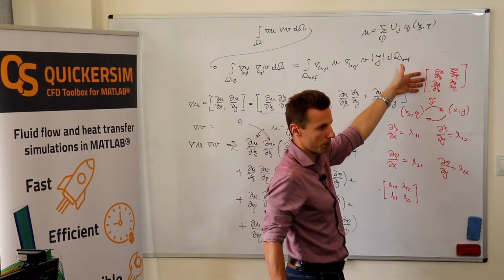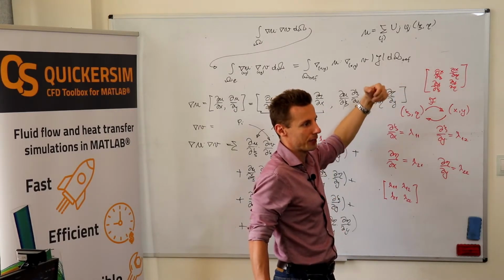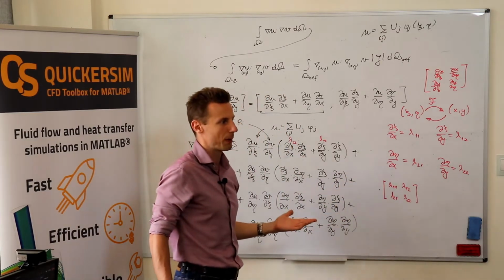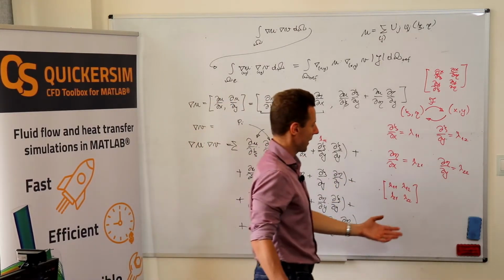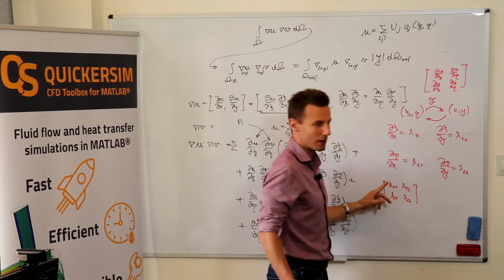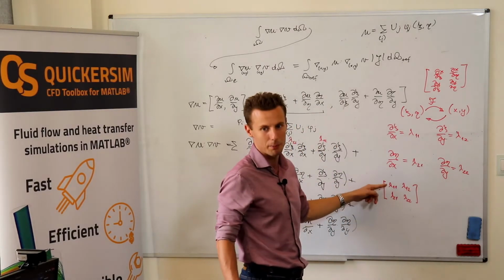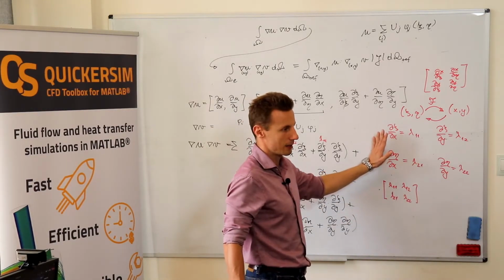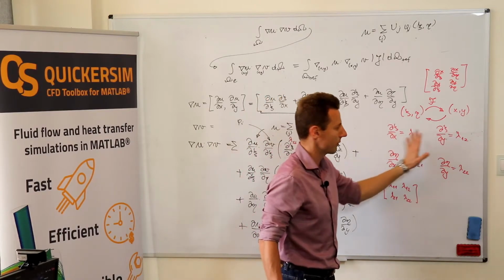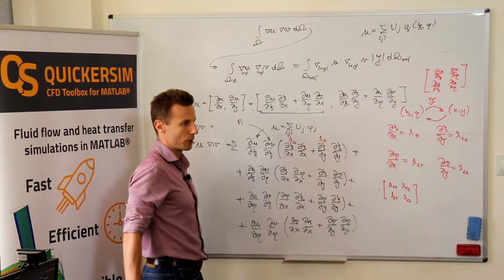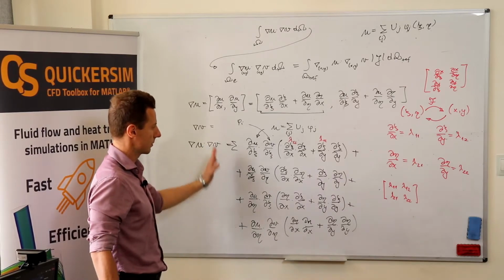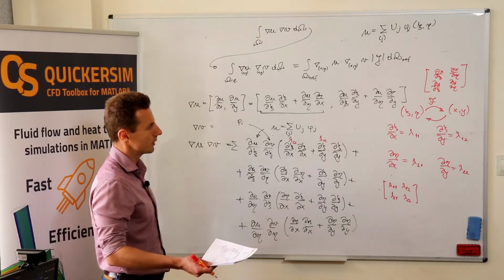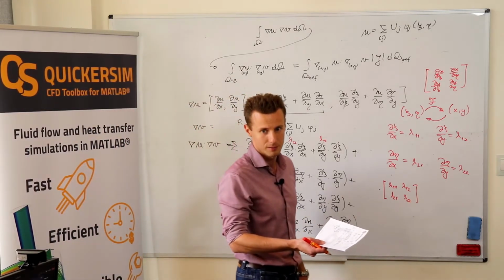You calculate the Jacobi matrix. Then you calculate the inverse of the Jacobi matrix, which is easy because it's 2 by 2, or 3 by 3 in the 3-dimensional case. And you've got the inverse, and you just need to identify, okay, this element is my lambda 1,1. This element is my lambda 1,2, etc. And there's an easy way to calculate these lambdas for each point in your element, and you only need to calculate where.